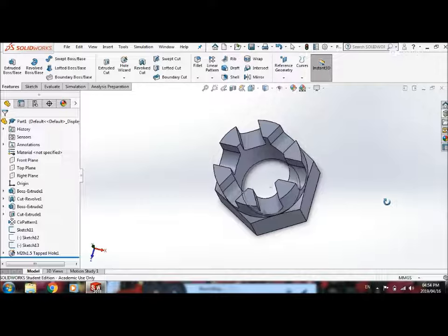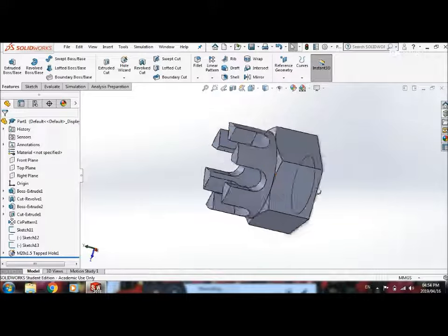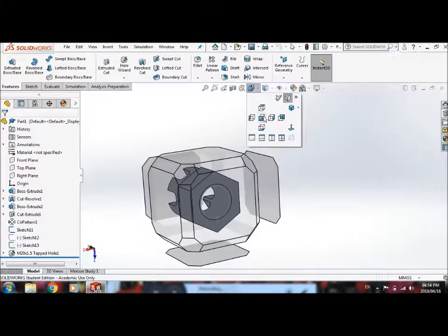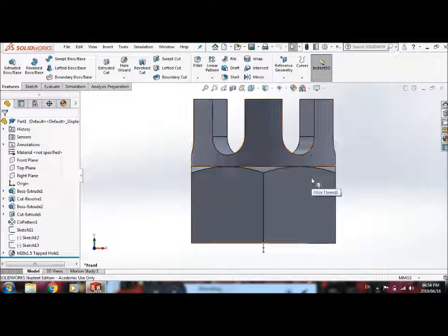So basically what SolidWorks now did is it drilled out on my nominal diameter like I would typically do, but then instead of drawing the detailed spiral, it just uses this sketch line to indicate that there's a thread. If I view it directly from the side, these dotted lines also show me that there's a thread. Right. So that's the way you would technically correctly thread something in SolidWorks.